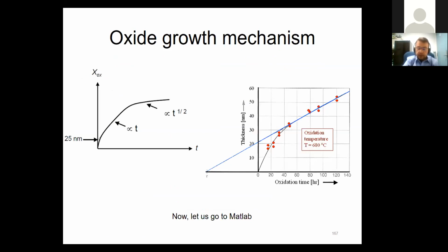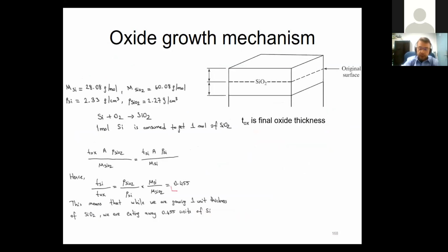We'll examine these things, the growth rates. I'm skipping that shortly, but again, emphasizing this in this very simple examination. Let's say that we originally had the silicon wafer level to be like this at this point. And then we totally grow an oxide of TOX, that much, okay? The level, since we are consuming the silicon, will drop. The new silicon wafer level will be much lower. So let's call this the consumed silicon, T silicon, that portion.